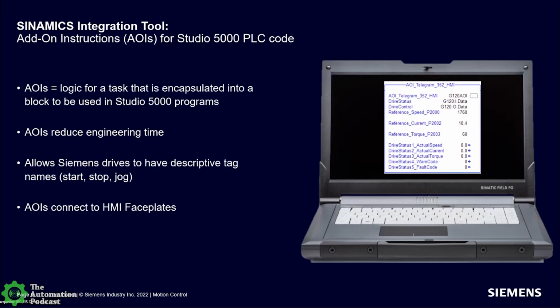Yes. So hopefully I do a good enough job explaining this. A telegram is kind of a Profinet word, and that's what I had to learn when I joined Siemens. Essentially, it's just a term for the cyclic communication between a drive and a PLC. So it's the control word and the status word, and there are different telegrams for different status and control words.